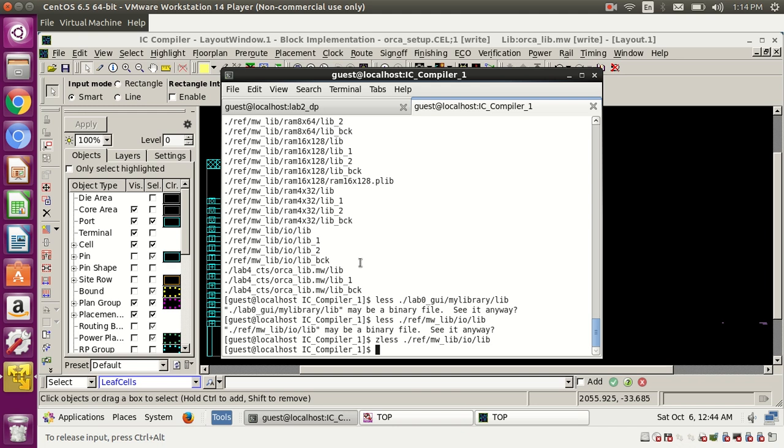Not that requirement. What I am asking is, I said clock gating is a cell, and internally it might be some logic. So what logic serves our purpose? The thing is, we have an input clock and we have an enable. Whenever the enable is there, then only the clock should go out. Whenever the enable is 0, the clock should not go out. So what logic will serve this? You say randomly AND or NOT.